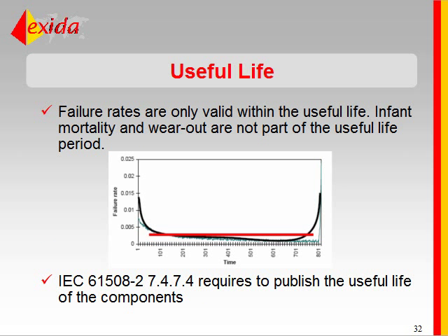The useful life is also an important part of the situation because components wear out. Many of you may think that this is an issue only for mechanical components, and in fact, it's a big issue for mechanical components. I'm thinking O-rings, I'm thinking springs, I'm thinking relay contacts. There are wear-out mechanisms in electronic parts.